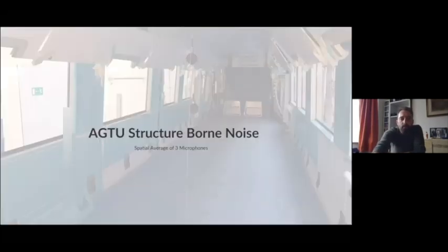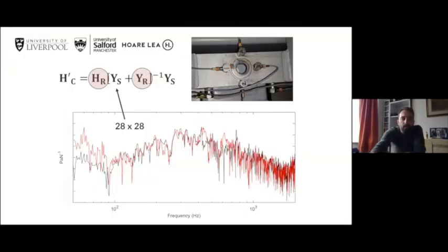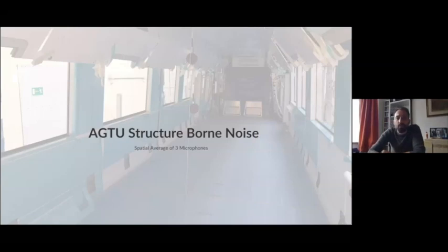So now we've measured this vibroacoustic frequency response function. We determined it from measurements on the source and receiver, and we've got the block force from the measurements in Italy, which have been validated. We can now multiply this vibroacoustic frequency response function by the block forces that we obtained, and we can use that to make a prediction of structure-borne noise inside the train. So this is inside the train. It's not finished fitted out yet. This was done as a validation measurement for testing the method.